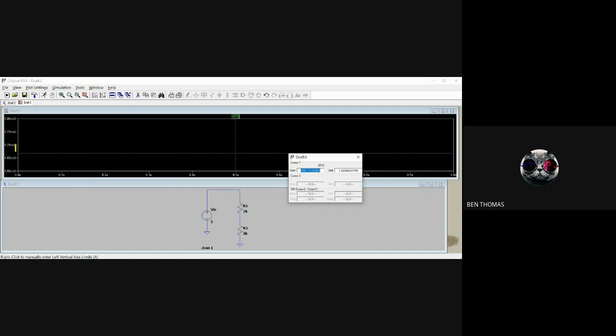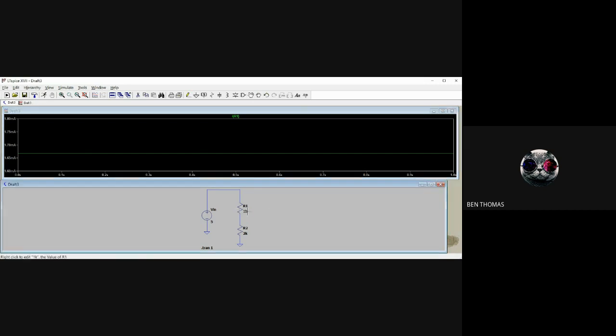I can specify the bottom as 1.65 milliampere and the top as 1.7, and change the tick to 0.001. Then you will get a more exact, accurate value. Yes, that can also be done. That's how you can find the current.